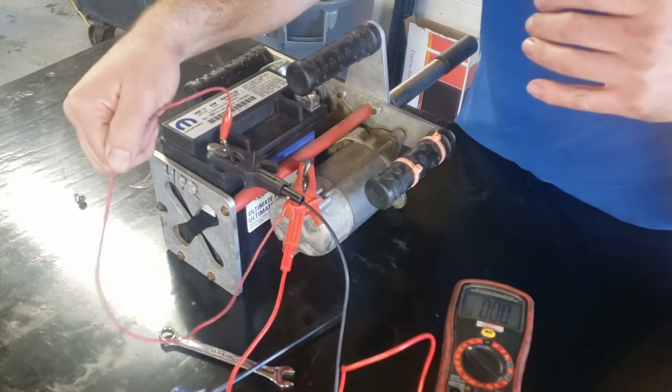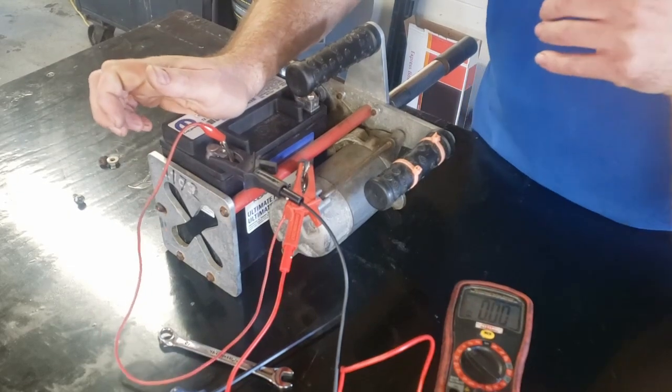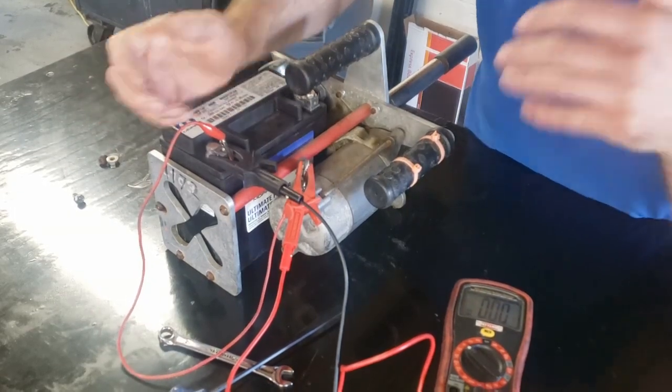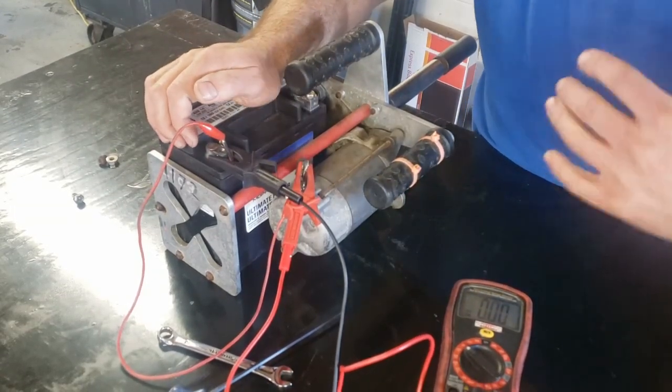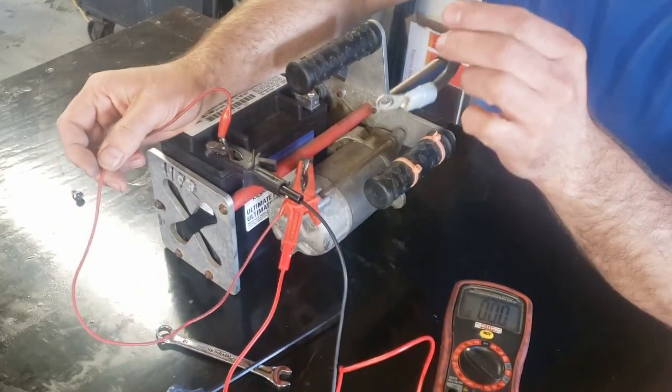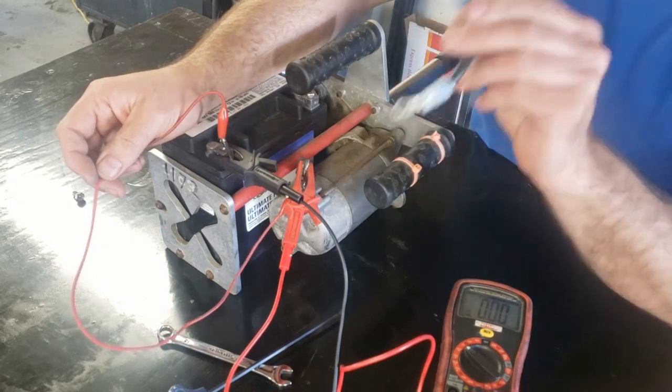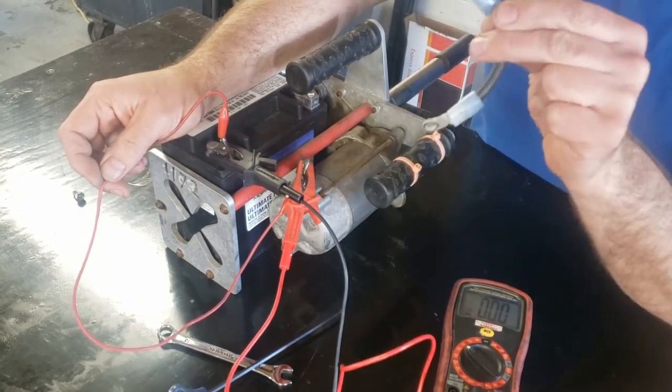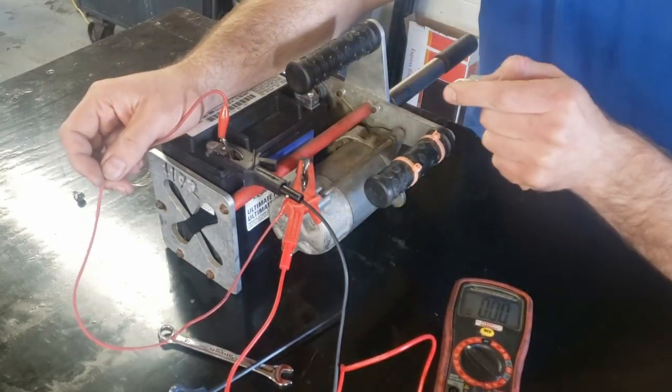You saw the puff of smoke from our wire because our wire got hot very quickly, and you saw the high voltage drop. Now, this is obviously a very dramatic situation, but it points out the fact that 2 wires with very similar resistance, when they're put into a high current situation, perform very differently, and we see a much higher voltage drop.